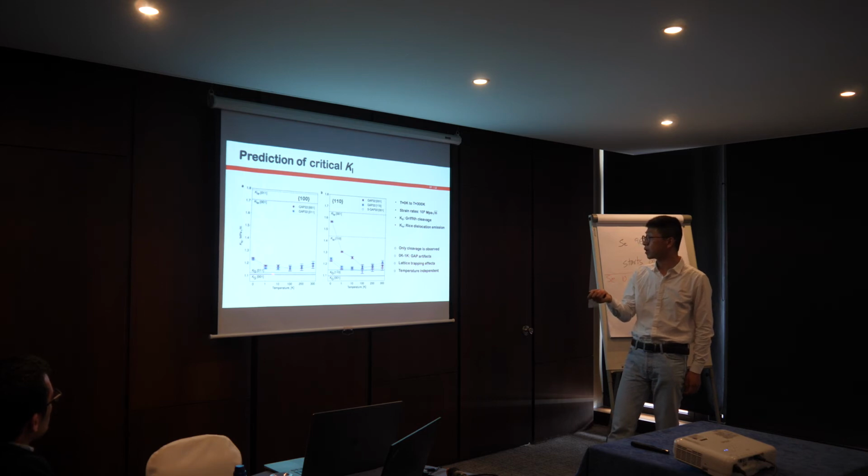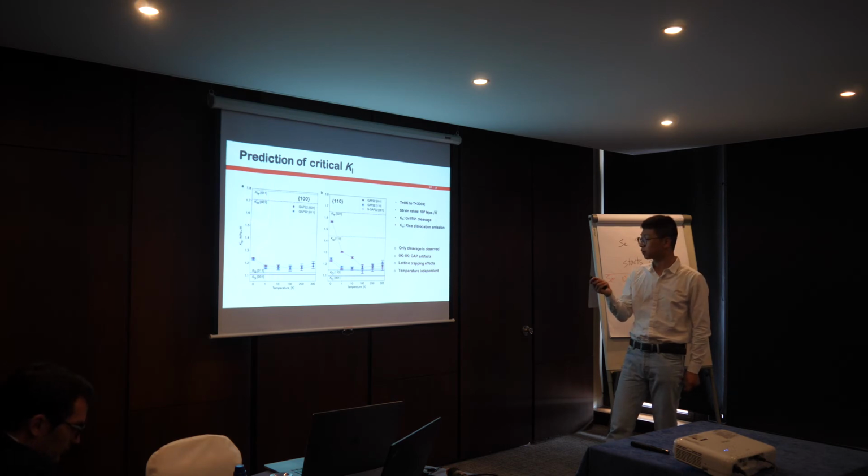And as long as cleavage takes place, K_IC is temperature independent, and it shows some lattice trapping effects. In atomistic simulation, it's expected to be the same as Griffith's prediction as long as the mechanism is cleavage, but it shows some lattice trapping effects due to the discreteness of the lattice.